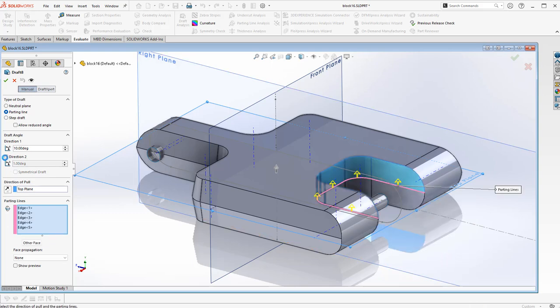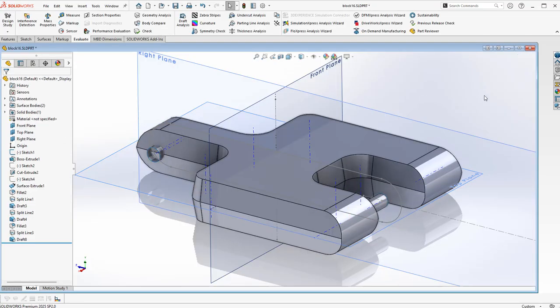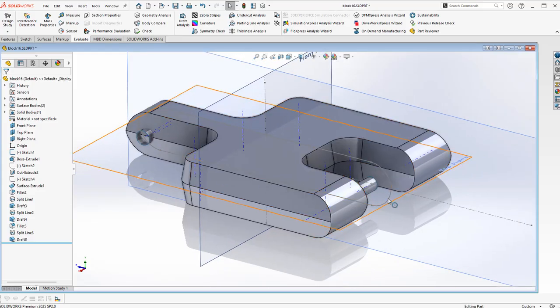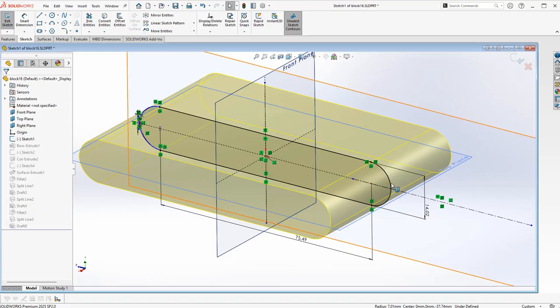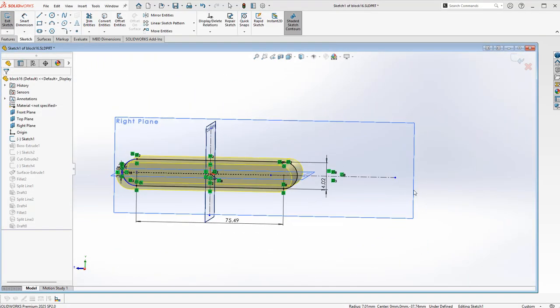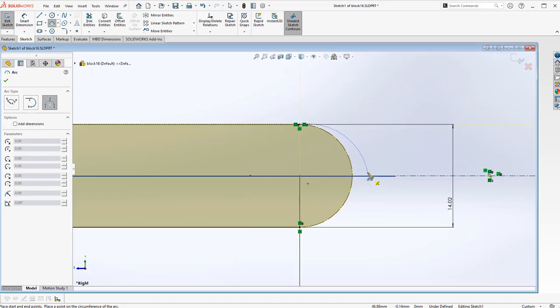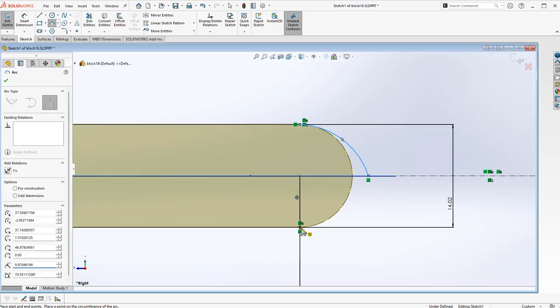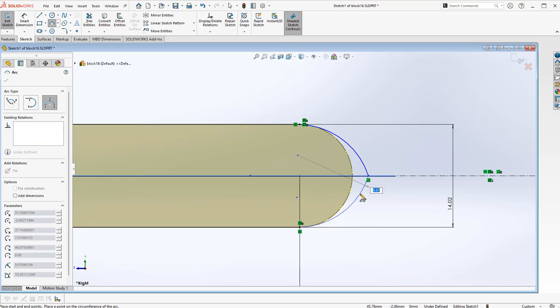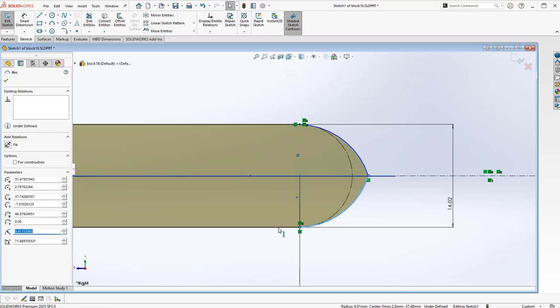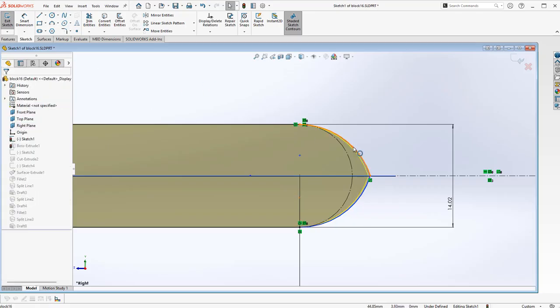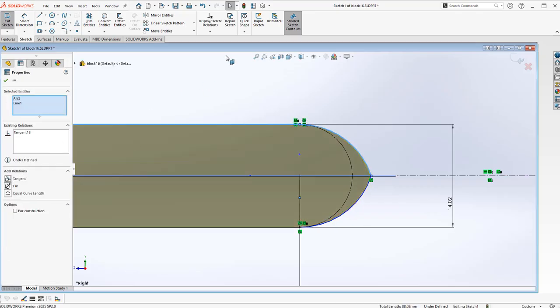We want preview to always be on. Symmetrical draft. There's preview, enter. Great, now I have to establish the same thing over here. So to do that, I double click on the sketch to take it back to the sketch, square up on it if you feel compelled to, left click, turn to construction geometry. Great, establish tangency here and here, a little bit redundant.